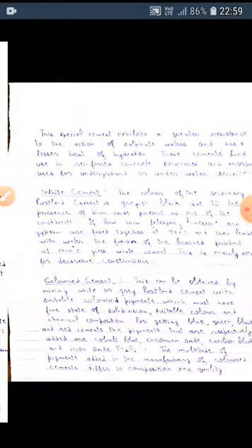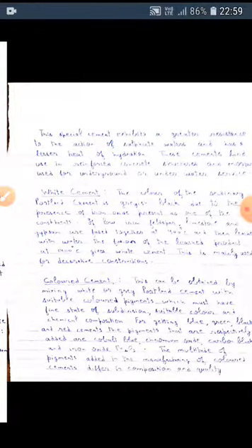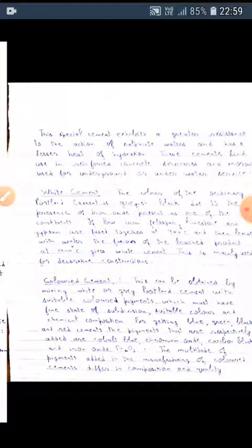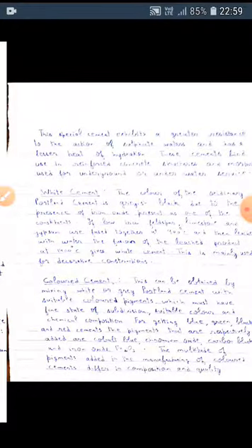According to compressive strength, two brands of slag sulfate cements are available in the market, brand 300 and brand 400. The setting time and the fineness of grinding of slag sulfate cements are similar to those of Portland cement. Mixing with Portland cement, while kept in storage or in preparing mixes, drastically deteriorates the properties of slag sulfate cement.